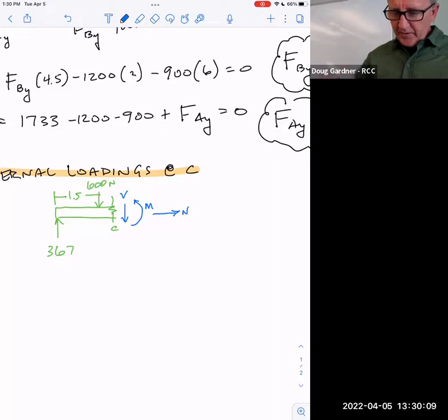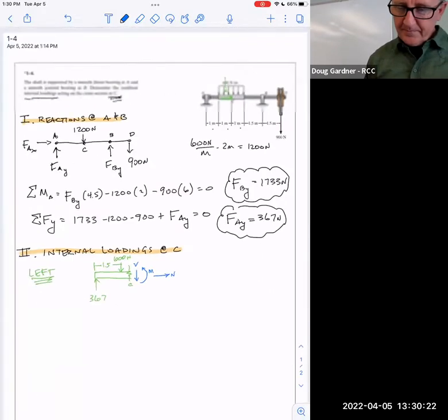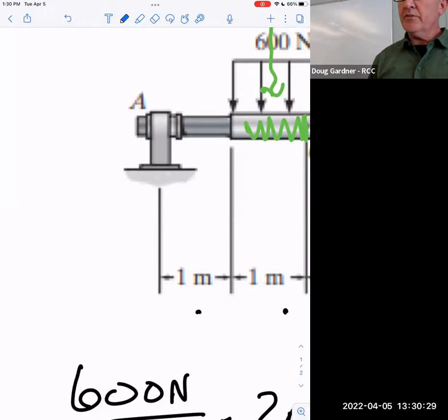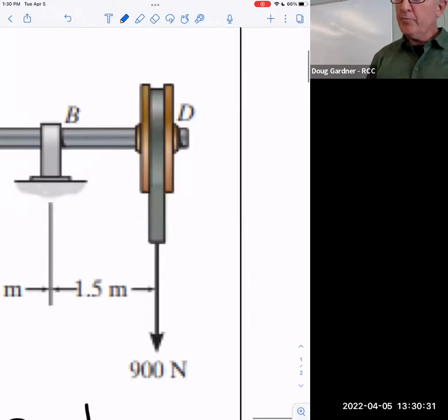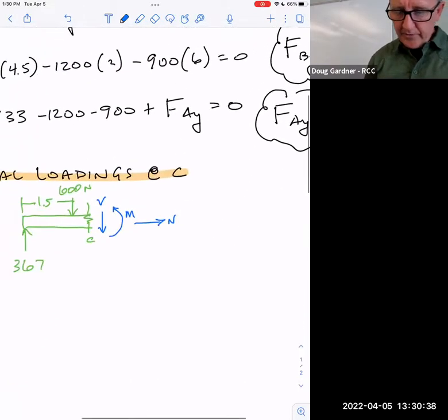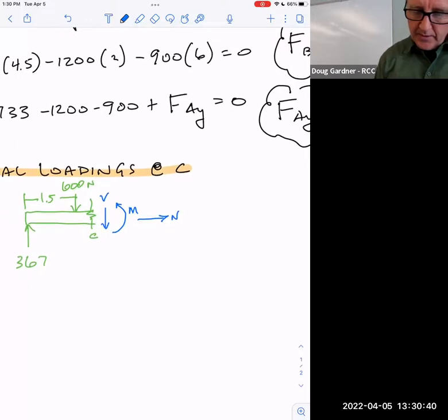The normal force we just drew is kind of like compressing, as opposed to, in a sense, I'd say it's more like it is pulling. It's taking that right side that we just broke and pulling it in this direction. And so if N was 7, then we're in trouble because we have nothing else to resist it. Well, A would have to resist the force, the bearing. Yeah, good point. If there was some normal force on it, then we do have a bearing there that could resist that, right? But if we were on the other side, it would just pull right out of there because there's no force in that journal bearing, right? So that's kind of interesting to note. But in our case, there's no forces anyway, so that's awesome.